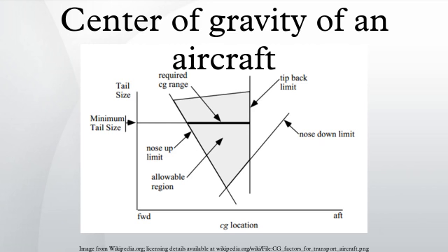Aircraft center of gravity calculations are only performed along a single axis from the 0 point of the reference datum that represents the longitudinal axis of the aircraft. Some helicopter types utilize lateral CG limits as well as longitudinal limits. Operation of such helicopters requires calculating CG along two axes, one calculation for longitudinal CG and another calculation for lateral CG.